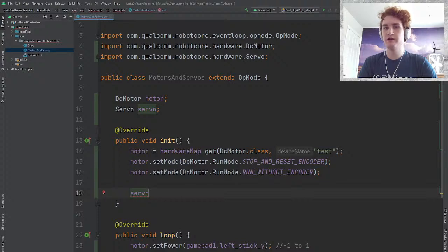They're useful because obviously you only have 8 motors on your robot, and sometimes you want a smaller packaging, but you want it to be able to rotate. Like if you look back at Freight Frenzy, a lot of teams spun the carousel using continuous rotation servos because you didn't need a motor for something that small.